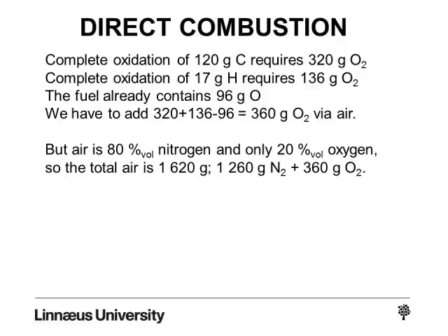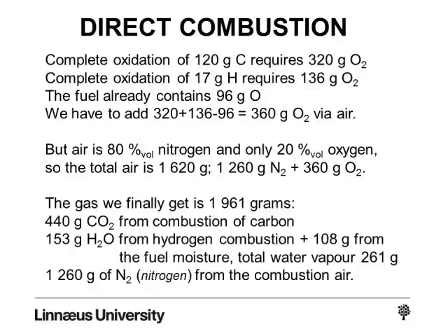So we have, from the beginning, 348 grams of fuel. We have to add 1,620 grams of air to oxidize it, and the gas we finally get then becomes 1,961 grams. Almost 2 kilos of gas is what we get.